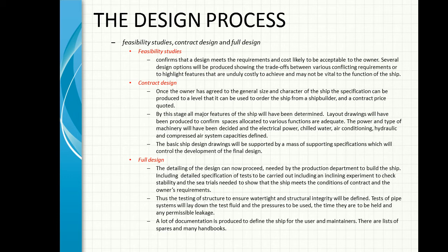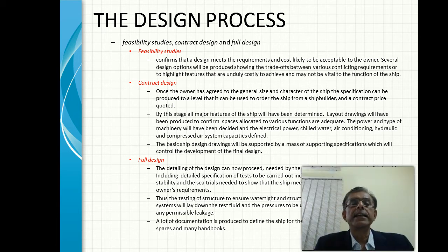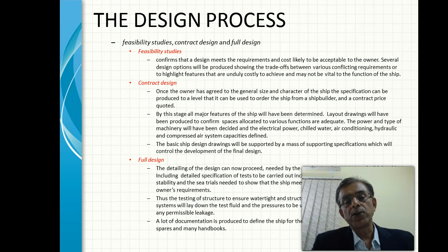Once a contract design is done, the full design phase starts, which is a concurrent process in which the structural designs, the detailed structural designs, the detail engineering designs, the outfitting designs are parallelly being processed. This literally continues for a period till the as-fitted drawings are made when the vessel is completed. So the naval architecture discipline is intimately involved in documenting the entire phases of ship construction.